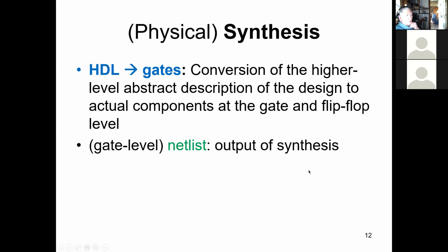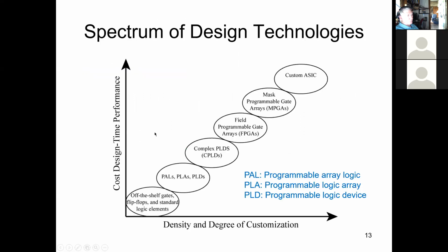And so sometimes you have to go mess with the mapping, routing, and placement step. We won't have to do that in our case because we're not doing anything that critical. But if you're really pushing the limits of speed, then you might have to.